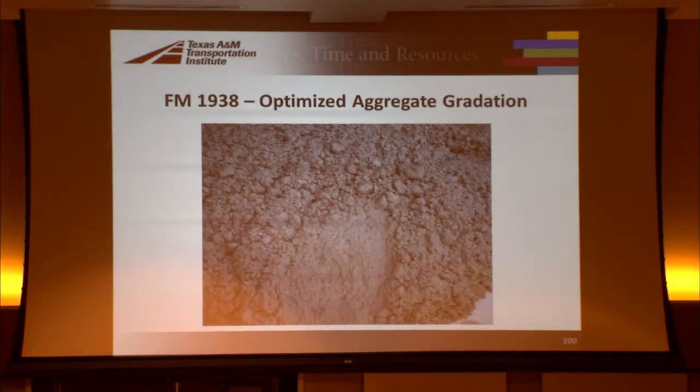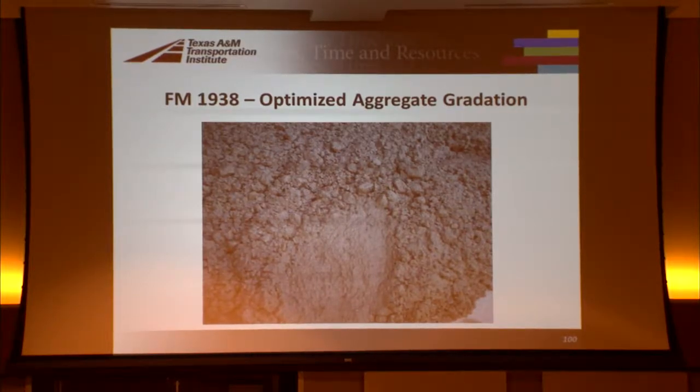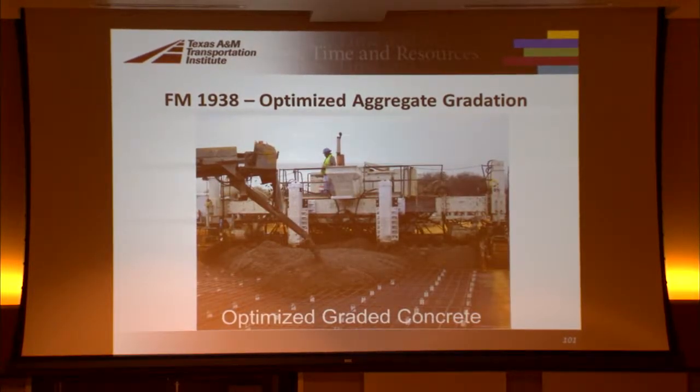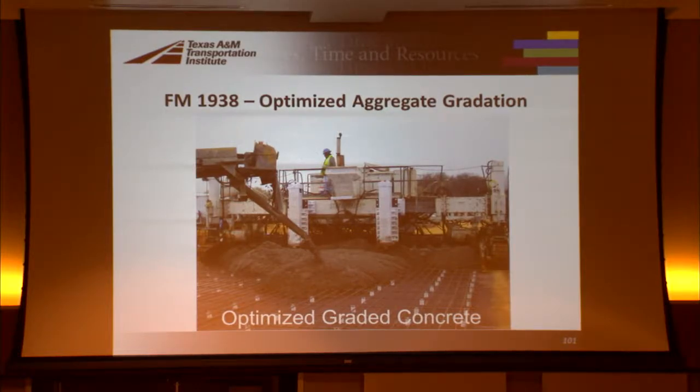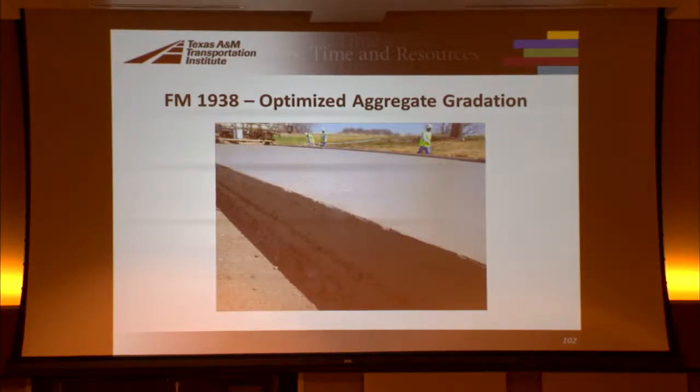Again, when you look at these mixes, they look really rocky. You can see how the paste comes up where someone put their foot on it. And we had a slip form paver. I remember when I was out here on the job, it did scare some people. I said, can we even finish that? But right behind the paver, it was really smooth. The paste came in nicely. But I think some people were scared of it because it just looked so rocky when you put it ahead of the paver.